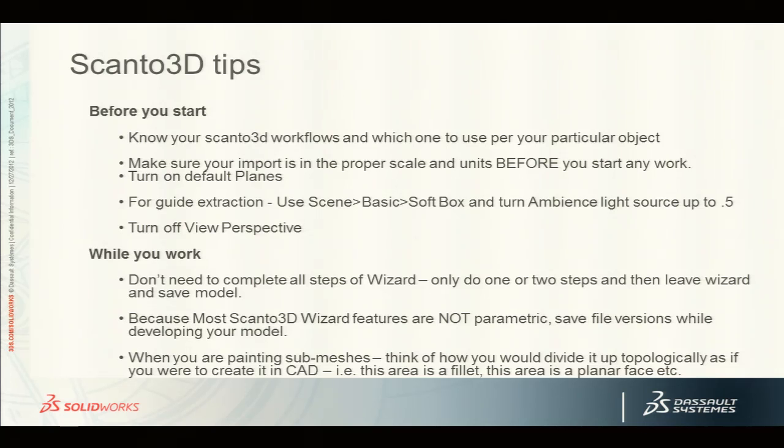Anyway, a couple tips. I'm just going to review a little bit, and then hopefully we'll have like 30 minutes left to do some live demo. So know what workflow you're going to use. Now I've educated you on the different workflows and what they're good for. If you have a real organic part, automatic surfacing might be the right thing. If it's a machined part, it's going to be guided surface extraction. If you want total control and you're really not sure about those two, go right with manual mesh and just model right against the mesh.